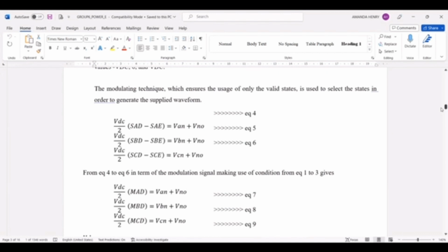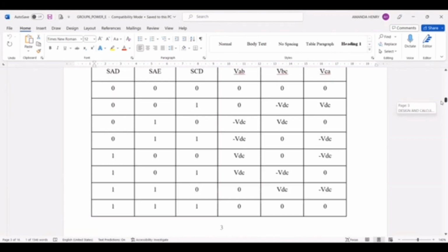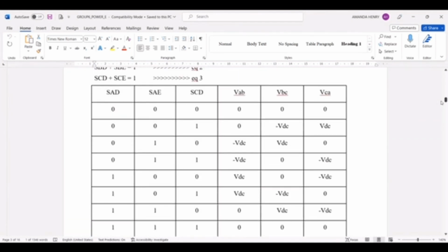Two of the switches represented in the table above result in an output AC line voltage of 0. The AC line current in the simulation freely recirculates through the upper or lower component. There is no 0 AC output line voltage in the remaining states. The inverter alternates between states to produce a certain voltage waveform.